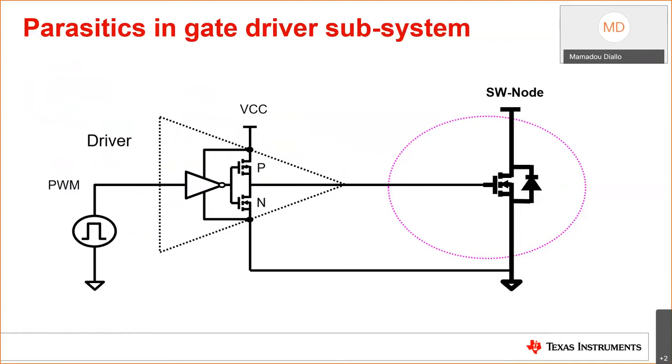All right, now we're going to go into our next phase, dealing with parasitics in the gate drive portion. If you notice previously, we started with the bias supply. We discussed biasing on the VCC supply. We also discussed biasing on the HB-HS capacitor, or bootstrap capacitor. Then we also looked at leaving functional pins open and how they impact the gate drive portion.